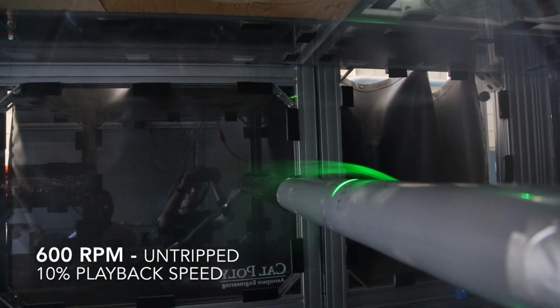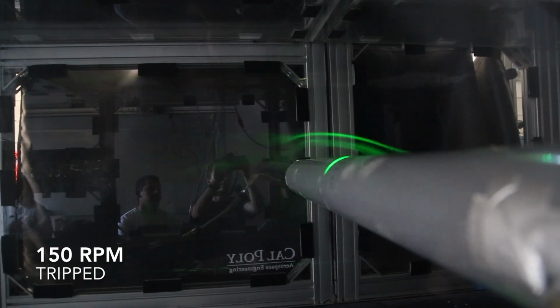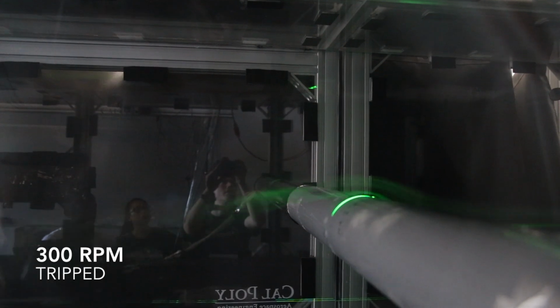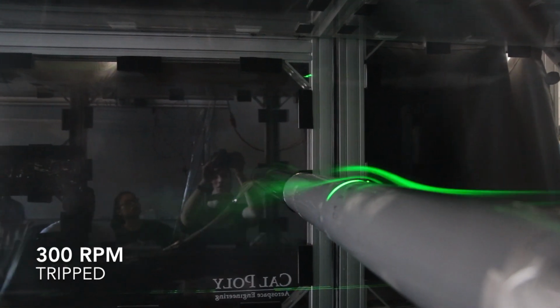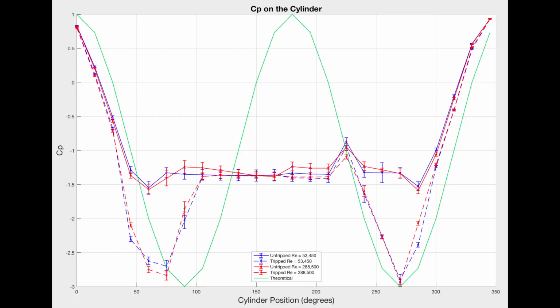When the flow over the cylinder is tripped, the boundary layer is energized, giving it more energy to remain attached to the surface. The locations of the sandpaper strips, installed 75 degrees above and below the stagnation point, were determined based on observing where the flow separated. This is clear in the plots of both CP and CD. It can be seen in the coefficient of pressure plot that the flow becomes disconnected around 75 degrees above and below the stagnation point, which is roughly 30 degrees past that at which the flow became unattached when the boundary layer was not tripped.